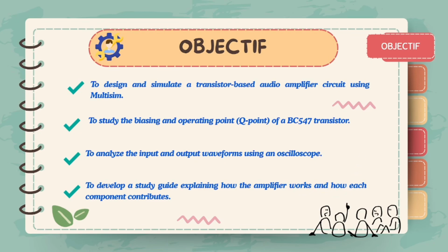Here we have explained that voltage gain is equal to Vout over Vin, which we can get as RC over RE. This gain tells us how many times the input signal voltage is amplified, and we can also verify this gain experimentally by measuring the input and output voltage with an oscilloscope or a voltmeter.